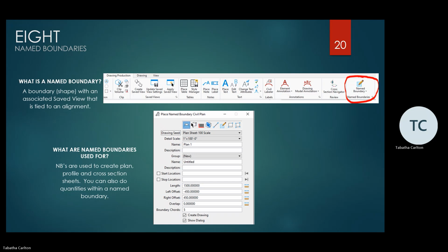Is it safe to say that the tool you're describing within OpenRoads is almost like parametric line work? The ORD geometry, yeah. That's all it is. It's lines that have rules behind them. It's rules-based geometry. You're going to find the bigger the project, they haven't worked out all the kinks with that yet. So I would say just be careful and pay attention to how you build it off your alignment, how you lay it out. Keep it simple, and use the right feature definition.